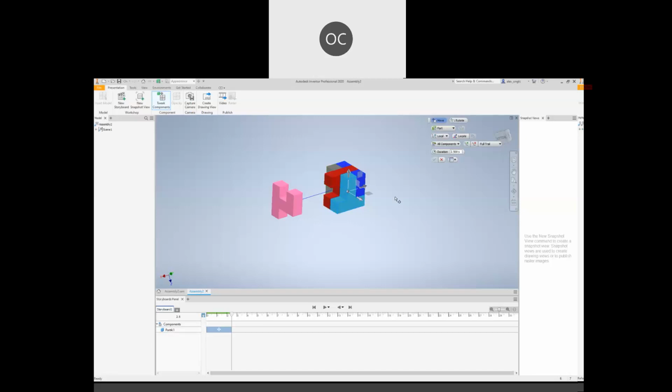For example, this one I want to follow this arrow insert. So I left-click and drag. I want it to have the same distance as the previous part, which is 20 mm. Once you key in your value here, click OK. You will see one track over here. This one is part number 2.